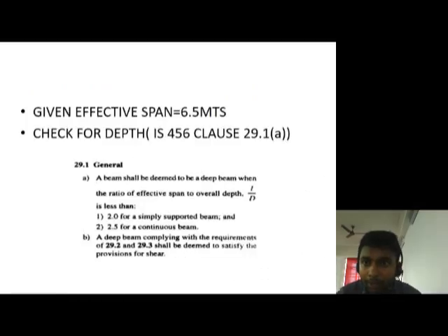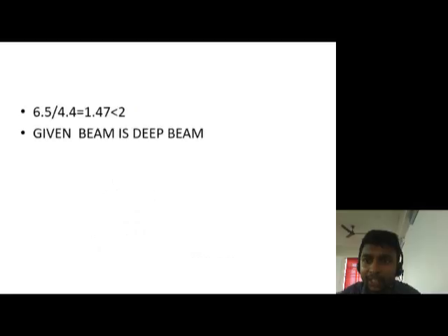From the formula L by D, the overall L by D, we will be calculating 6.5 by 4.4. We will be getting around 1.47. It was less than 2, so the given beam is a deep beam.